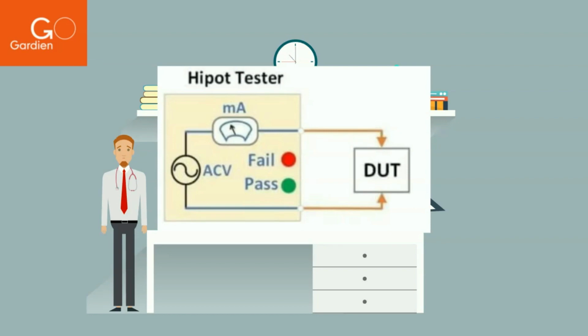Many standards, such as IEC 60950, specify an AC test voltage that is twice the operating voltage plus 1000 volts. Most allow the use of either AC or DC voltage. The test setup and procedures are identical for AC and DC, although the DC level should be equal to the AC voltage peak. The test time is normally 1 minute, but in some situations, such as high-volume production testing, a shorter test time may be permitted at a higher voltage.